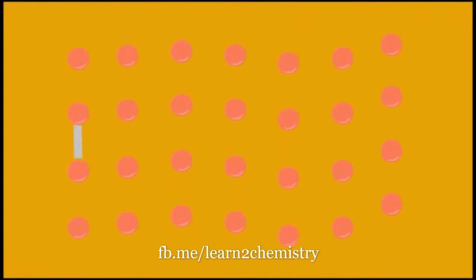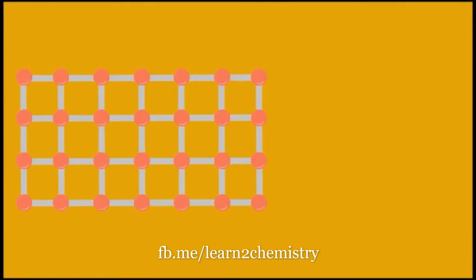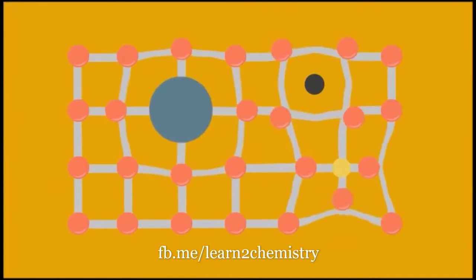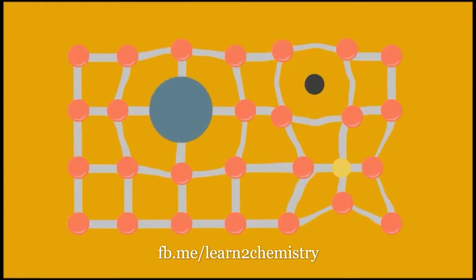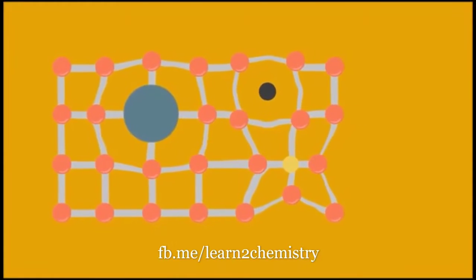So, we take our grains of iron atoms and our alloying additions, which often have a different atomic size. For example, carbon is small, nickel is slightly smaller than iron, and molybdenum is slightly larger than iron, and add them together and we get a distorted structure. When we add atoms that distort the atomic structure, this makes it more difficult for the atoms to move around and makes the material stronger. Depending on the type and amount, we can make a metal much stronger.